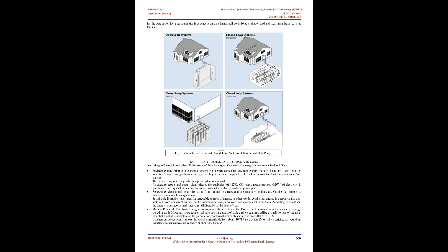Disadvantages of geothermal energy, according to Energy Informative, 2020. Environmental issues. There is an abundance of greenhouse gases below the surface of the Earth, some of which migrates towards the surface and into the atmosphere. These emissions tend to be higher near geothermal power plants. Geothermal power plants are associated with sulfur dioxide and silica emissions, and the reservoir can contain traces of toxic heavy metals including mercury, arsenic, and boron. However, it is needful to note that regardless of how it is being considered, the pollution associated with geothermal power is nowhere near that of coal power and fossil fuels.